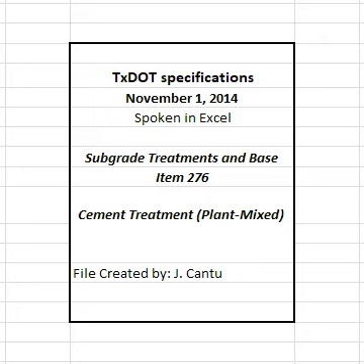Complete compaction within 2 hours after plant mixing water with dry material. Complete compaction of the final lift within 5 hours after adding water to the treated base used in the first lift when multiple lifts are permitted. Moisture content in the mixture at the plant may be adjusted so that during compaction it is within 2.0 percentage points of optimum as determined by TEX 120E.